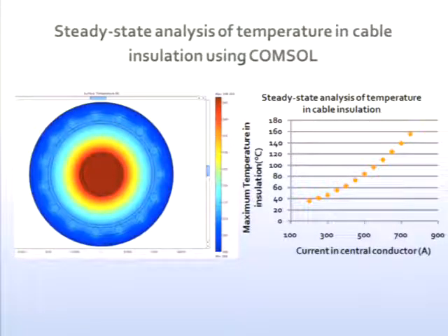Temperature. Okay, so these cables get hot. I think some in the audience might dispute that, but what we did was to go ahead and do a finite element calculation of the temperature distribution in a cable. So heat is being generated in this region here by the current I squared R, the current flowing through the central conductor. And we simply specify the outside temperature here as being room temperature. We said we'll put no current through the concentric neutrals. What sort of temperature distribution might we expect?